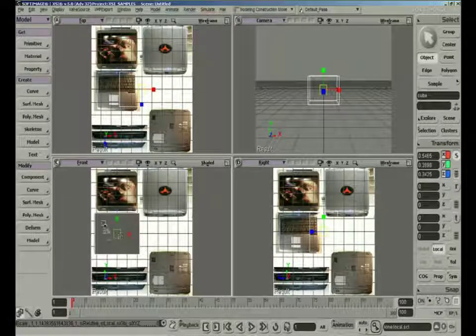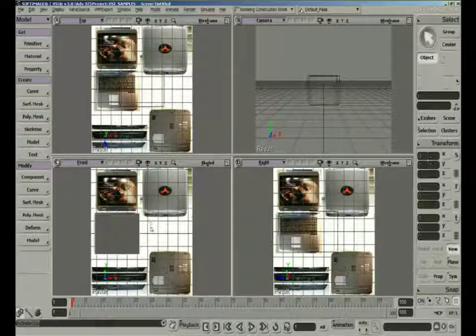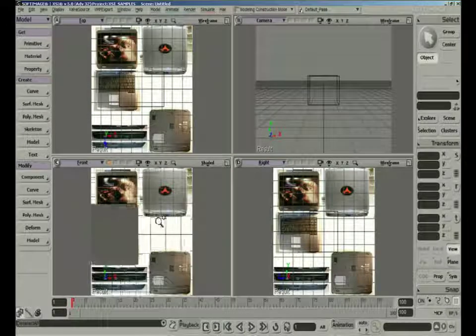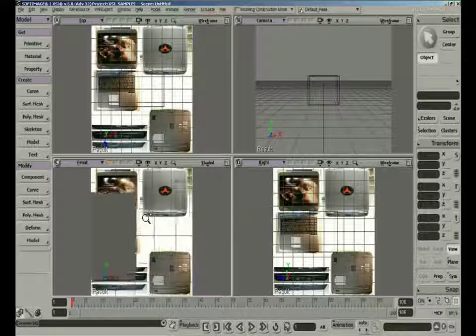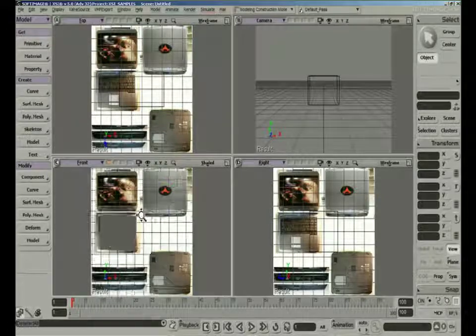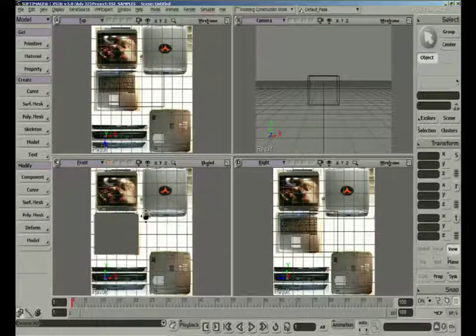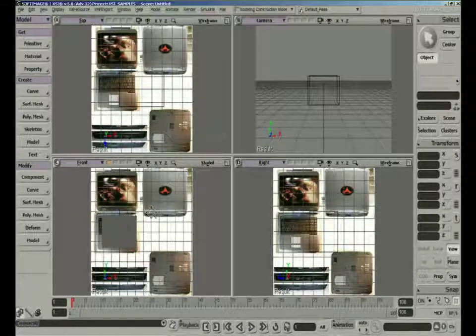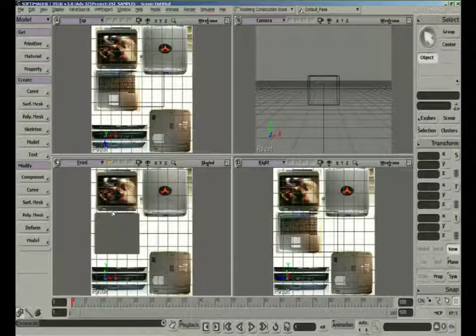Now right now would be a perfect opportunity to save a camera memory by clicking the middle mouse button on any of the available camera memory slots. This is going to be useful because if you happen to accidentally zoom or move your grid, it can be very difficult to return to exactly where you were. Once it's recorded, all you have to do is left-click on the slot, and you'll return right to your previous position.